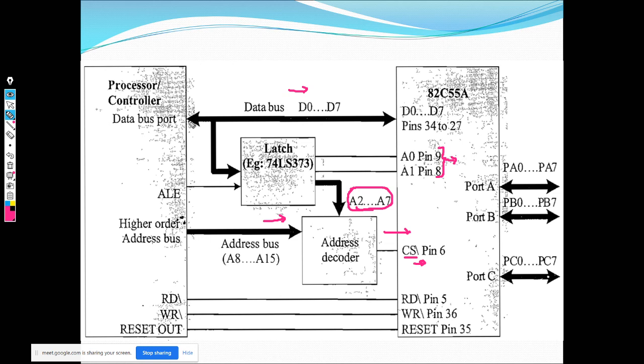As you see, there is only one data port and address port coming out of your microcontroller. However, outside of this PPI, the 8255A, you're going to see three: port A, port B, port C. One typical, popular example for this 8255 is the traffic light.